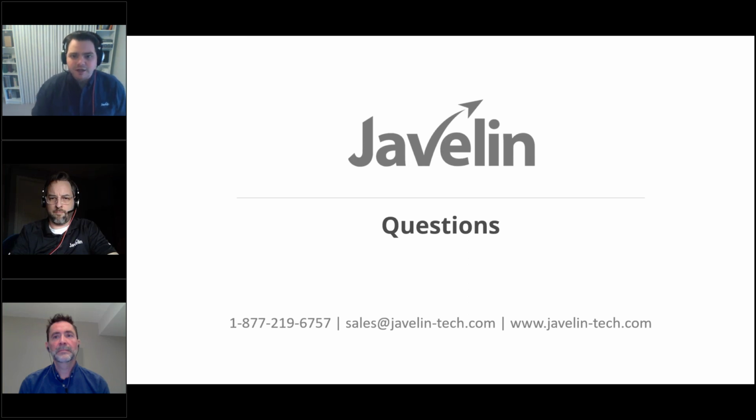The biggest thing to keep in mind when it comes to the SQL is the licensing. Previously, SOLIDWORKS PDM would come with a license of SQL standard 2014 that was runtime restricted, and it does not have software assurance with it, which means it cannot be installed in a cloud environment. So you have to have a version of SQL that has software assurance to use it in this environment. If you already have that, great. If not, one of the benefits with both Azure and AWS is that you can bundle it with your monthly fee. So it's a really cost-effective way to get the latest version of SQL and benefit from some of the improvements in performance that come from that.